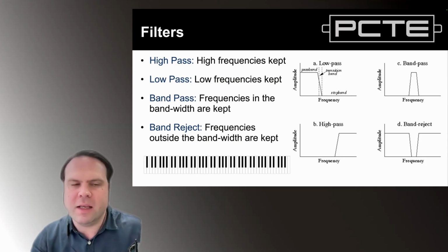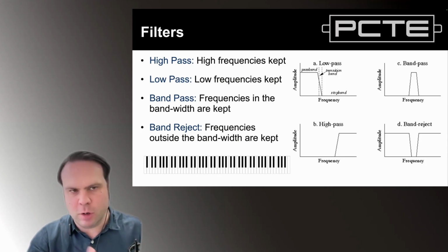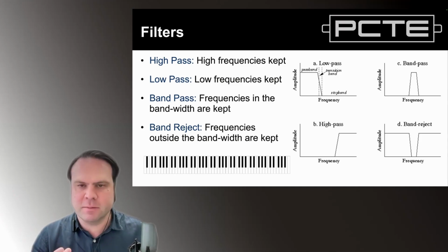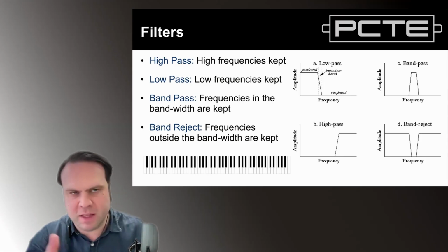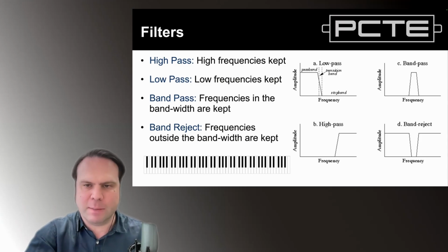It will only allow frequencies below its lower frequency or above its higher frequency. There's very little case you would use a band reject filter in this application, but you would use particularly a high pass filter, or perhaps a band pass if there was some reason to ignore results of very high frequency, maybe some sort of interference on your signal.